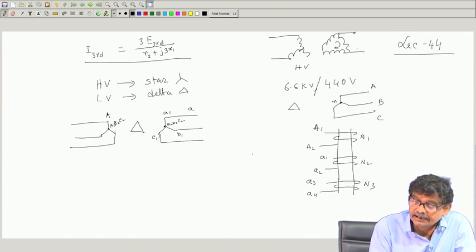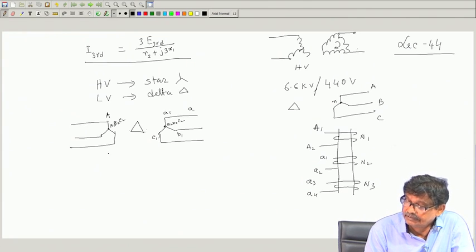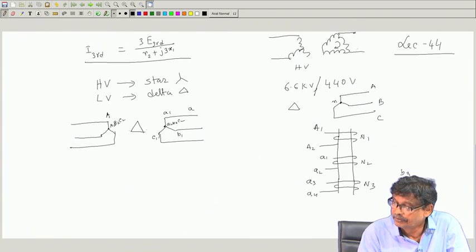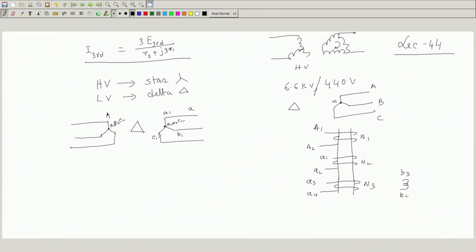And this one I have connected in delta, this A3, A4, similarly you will have B3, B4, I think you are understanding what I am telling, and you will have C3, C4, like the other two limbs, and these I will connect in delta, got the point. So, you connect them in delta and three terminals will come out.